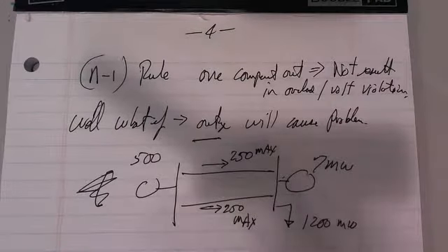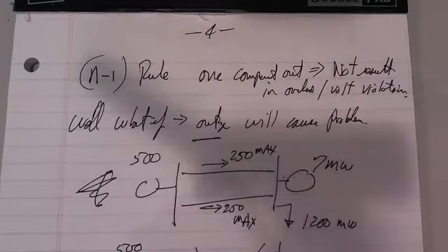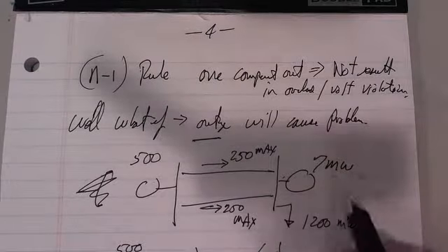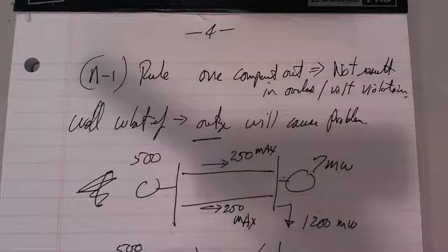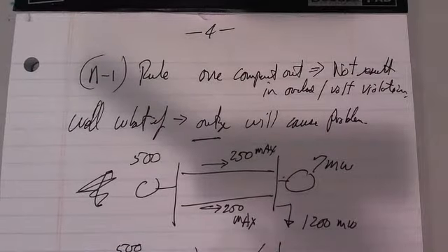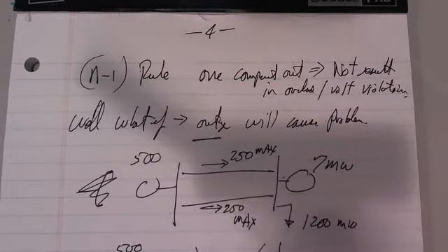Well, let's say we lose the top wire, and the circuit breaker is open, and now 500. We're assuming that these can just carry this. So now 500 all comes down here, and you've got 500 coming in through here and 250 capacity. And I can tell you what would happen there immediately. Everything opens up.